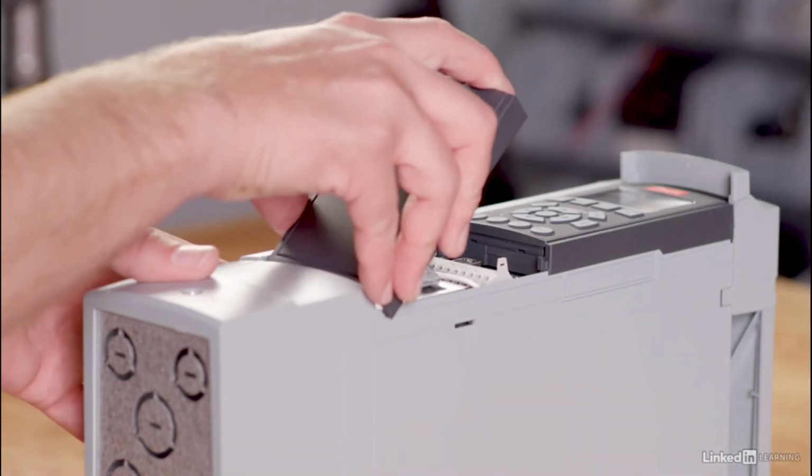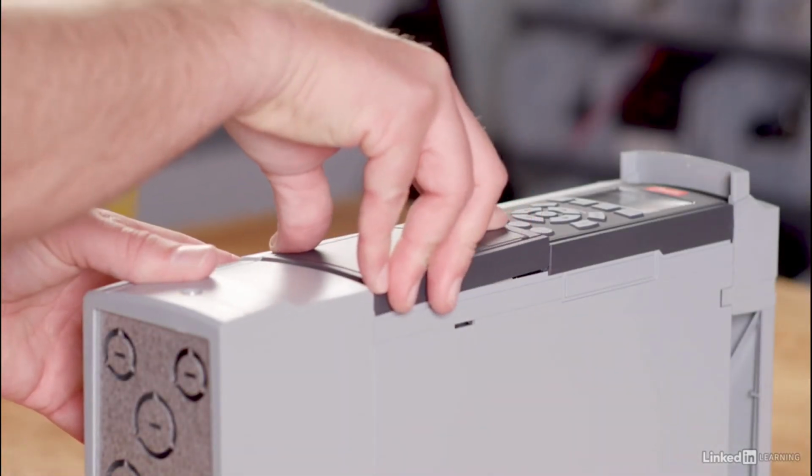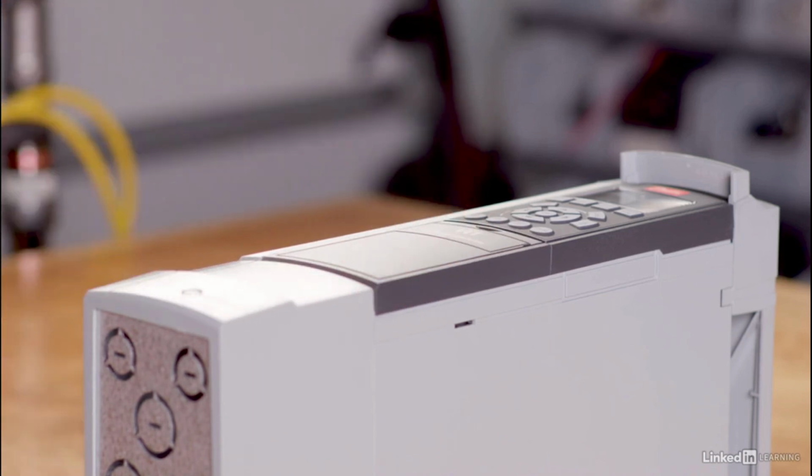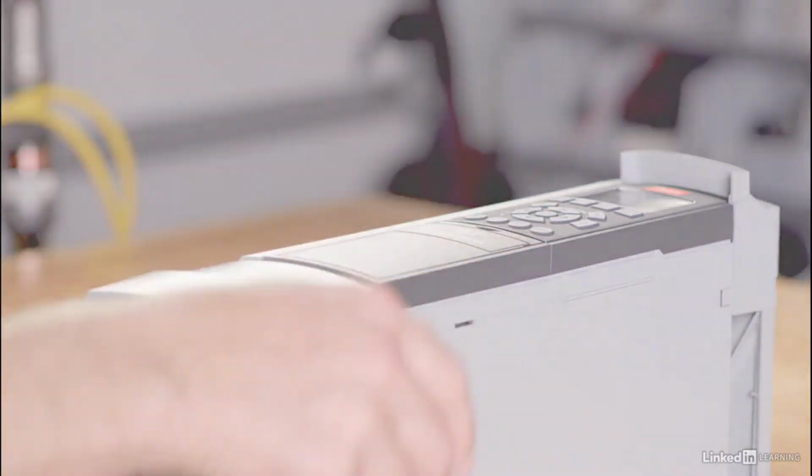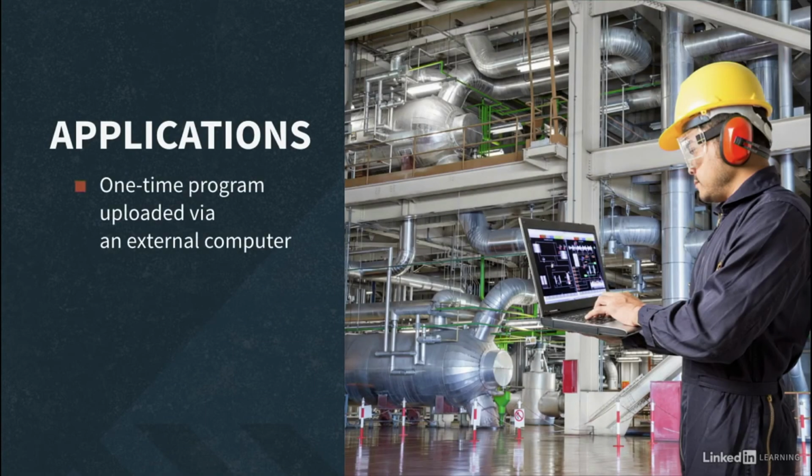Here we see a user interface for a variable frequency drive that can be programmed manually by pressing the keypad buttons and entering the parameters desired. In addition to this, many variable frequency drives are capable of interfacing with a standalone computer so that a one-time program can be uploaded into the VFD microprocessor, or continuous commands from the BMS system or temperature control computer can be sent to the VFD to match up with other parts of the building.